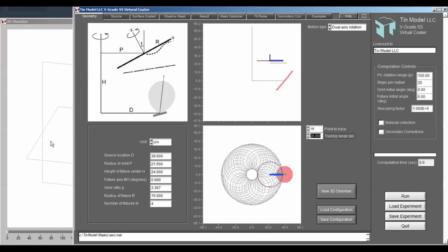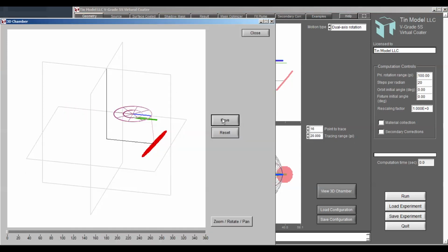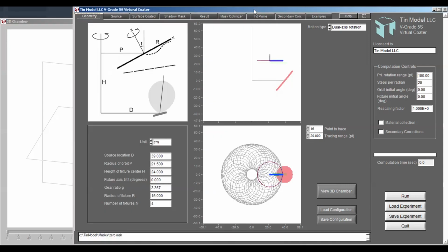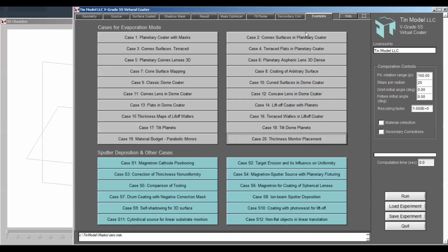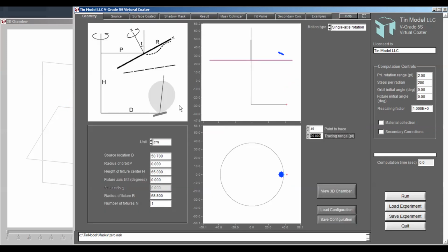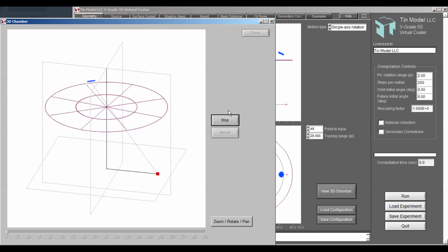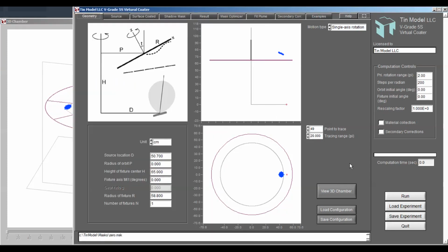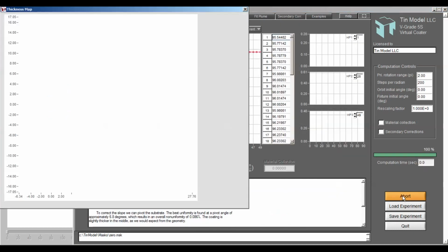You may have to use 2 or 3 or even more masks in order to maintain stringent uniformity requirements. I would like to mention that there are other techniques for maintaining thickness uniformity when the target becomes eroded through use. For the time being, let's start with the common technique of employing correction masks.